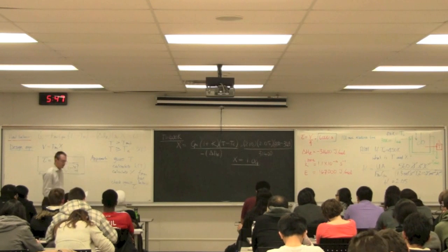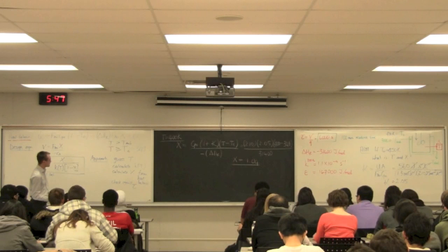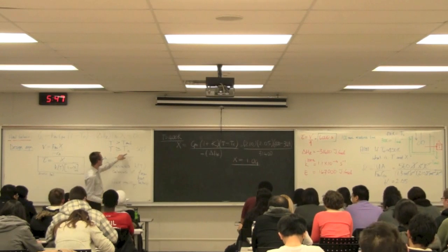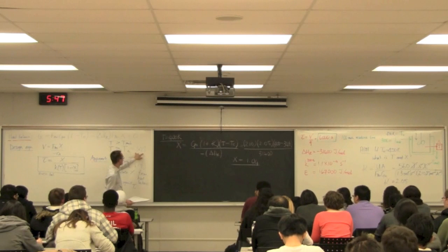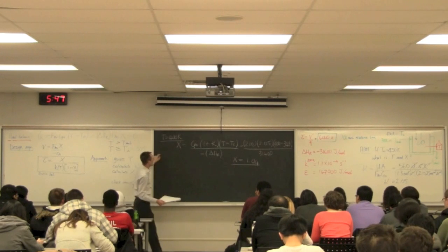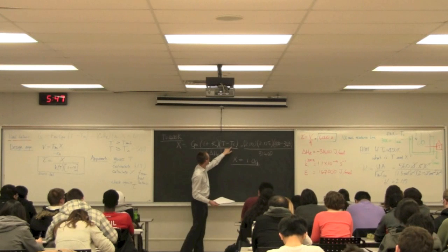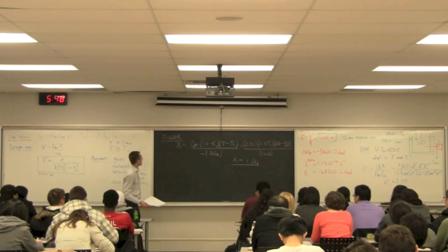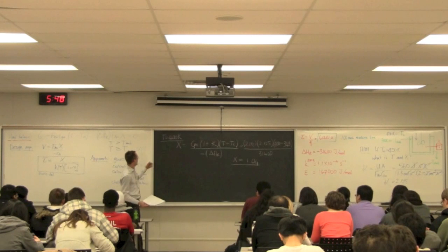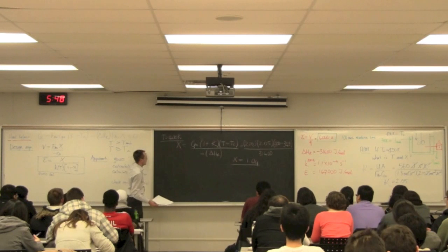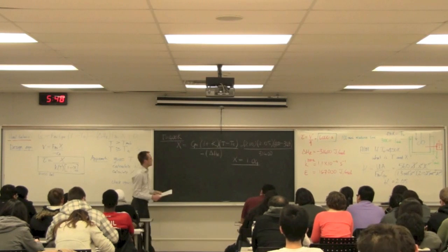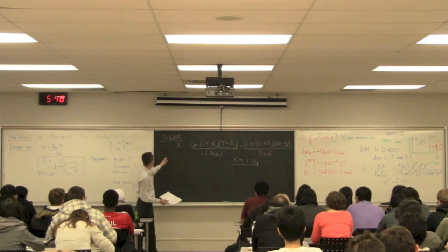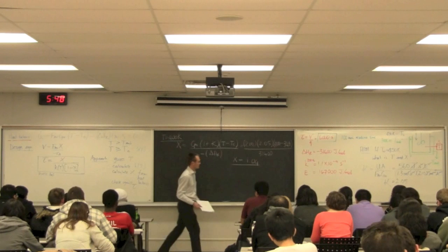Actually, one thing you should confirm for yourself is that if I substitute in temperature at 349, T minus Tc, 349 minus 349, I'm going to get zero conversion. So any value of temperature below 349 will give you a negative conversion, again indicating that that's a poor initial guess. So we know for sure we're somewhere between 349 and 400 Kelvin.